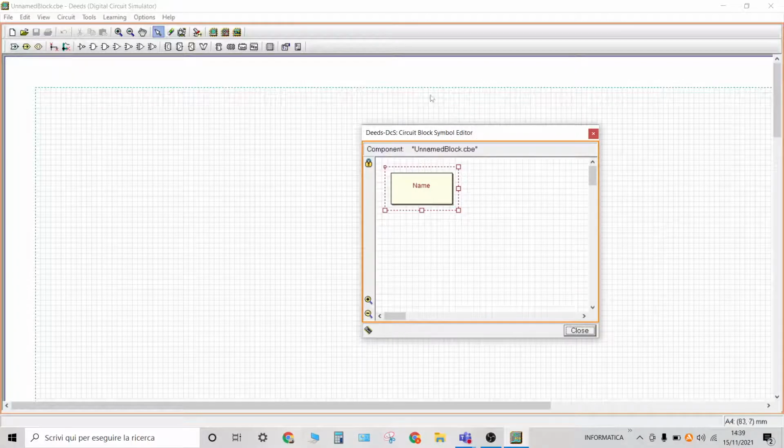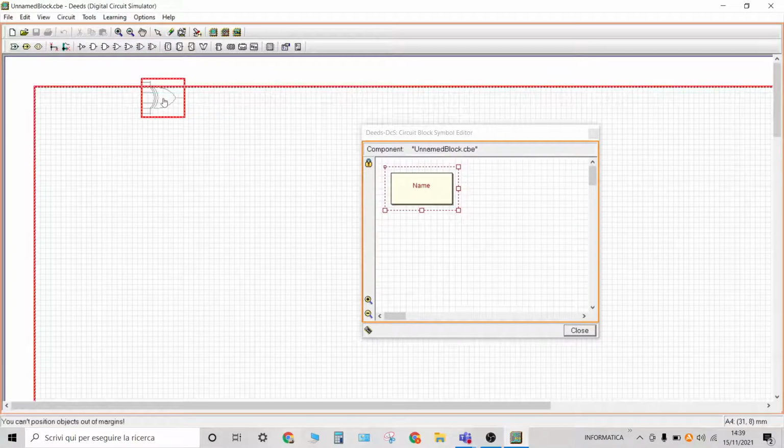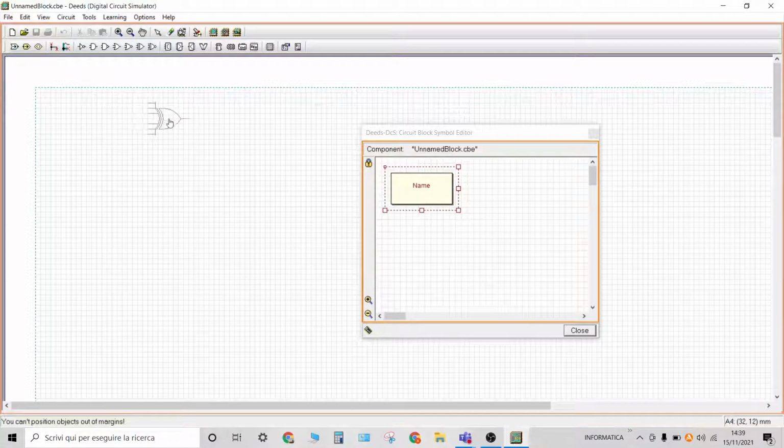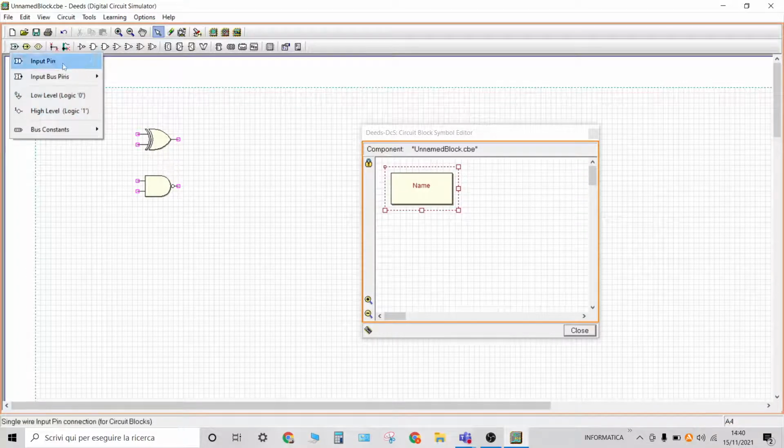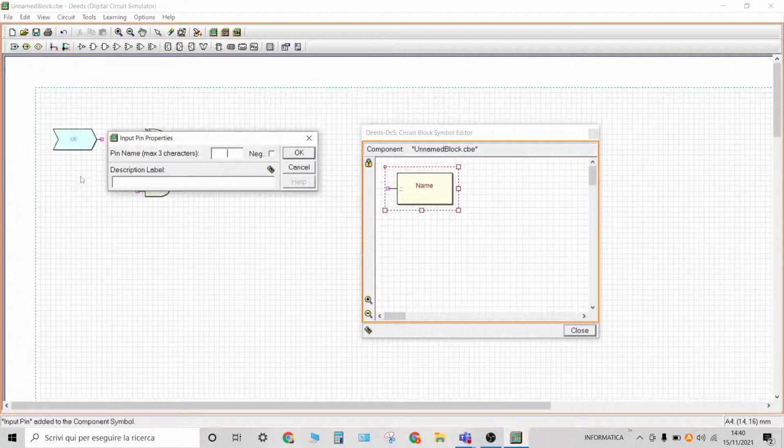Obviously, you could implement also a multiplier if you want. Not today, not at this lesson, but also in that case, you could use a hierarchical project by defining a custom component. Obviously, in that case, the custom component could be the basic block of the multiplier, composed of a full adder and an AND gate. Okay.